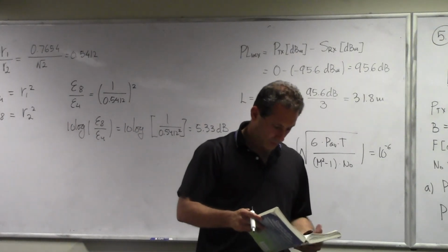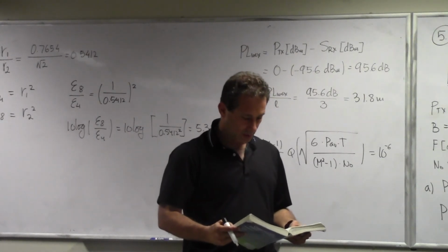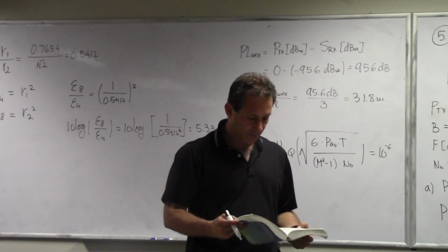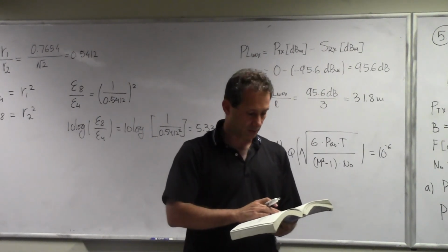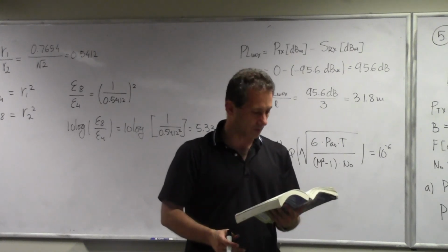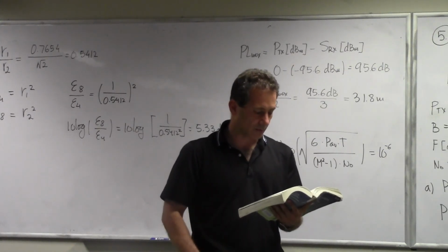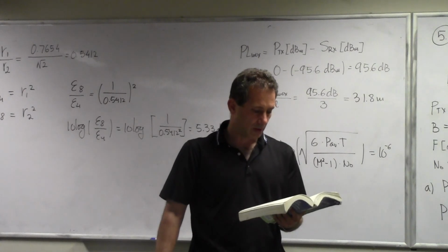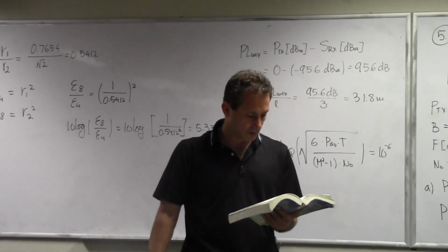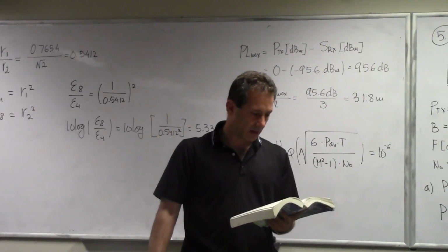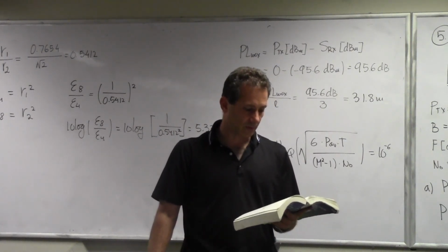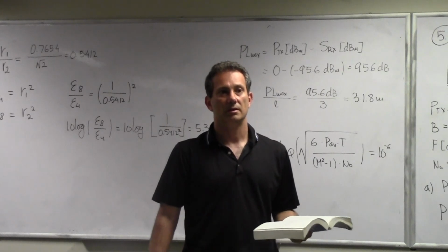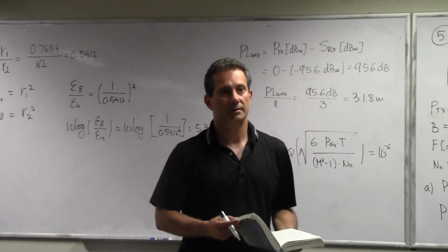Or there's figure 7.55, where I can just give you that figure. You can read from the figure for a given probability of error. If I say, for example, that you're signaling with a 4-level PAM and the desired probability of error is 10 to the minus 6, then you can read from the curve that you need about 15 dB. And then you go from there.